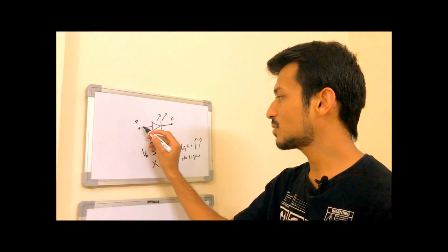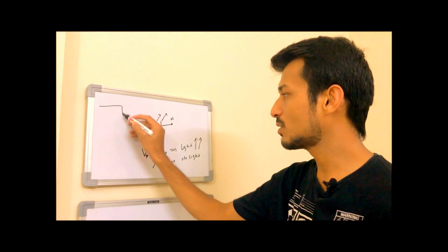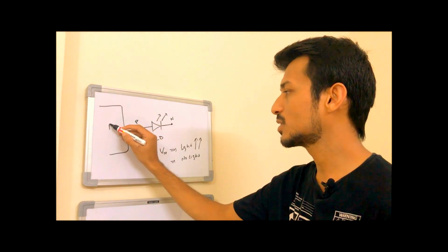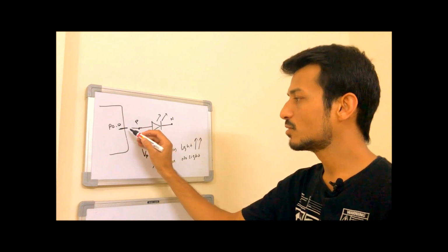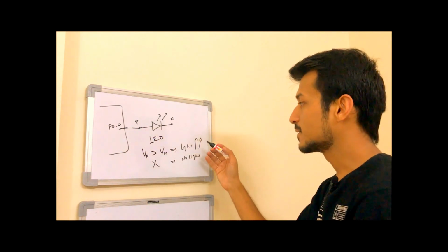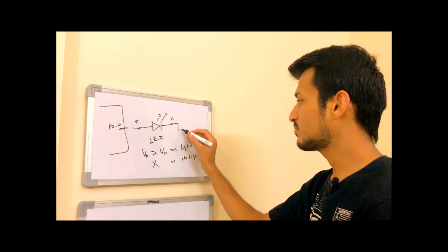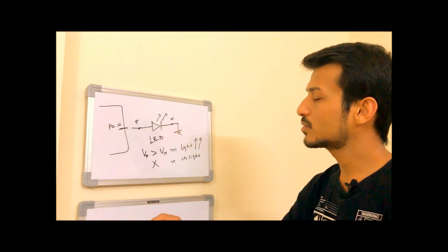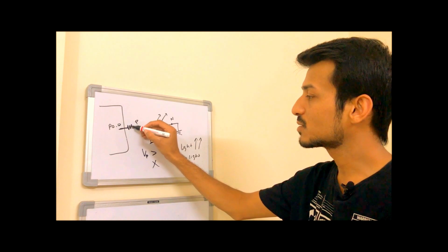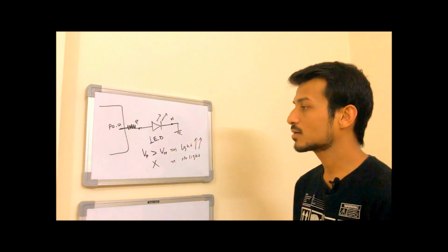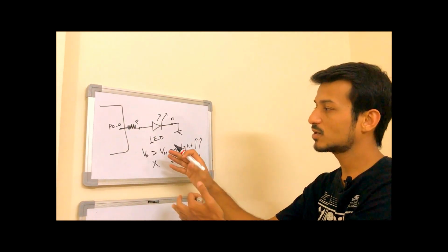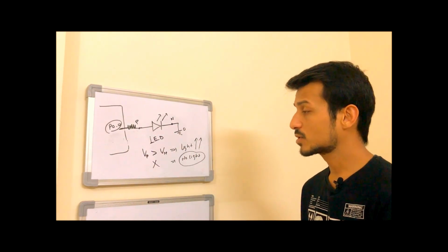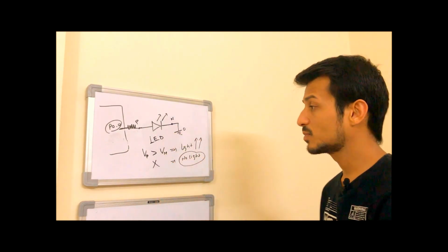So we will be connecting the P terminal of this LED to one of the input output pins of our microcontroller. So let's say port 0.0 we are connecting here, and the negative terminal is always grounded. We will not connect this terminal directly to the LED. We will have some current limiting resistor so that the current that flows into the LED can be limited by this resistor. So that's how the LED is connected in my board.